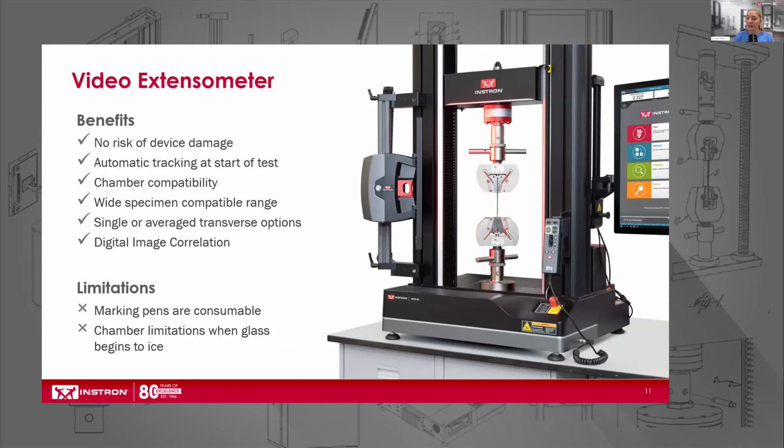If minimizing the hassle of preventative maintenance sounds appealing, or you need a more flexible extensometer option that will not only cover your testing requirements today, but applications that might get thrown your way in the future, then I'd recommend a non-contacting extensometer. So the advanced video extensometer, or the AVE, is a video-based extensometer that measures strain by tracking marks on the specimen surface.